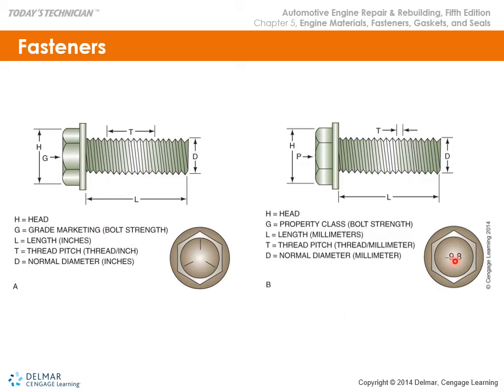Okay, so thread pitch is important, that we have a thread pitch gauge in our toolbox and we can quickly find the thread pitch. It'll narrow down exactly what that bolt is. But looking at the head is a good place to start also.